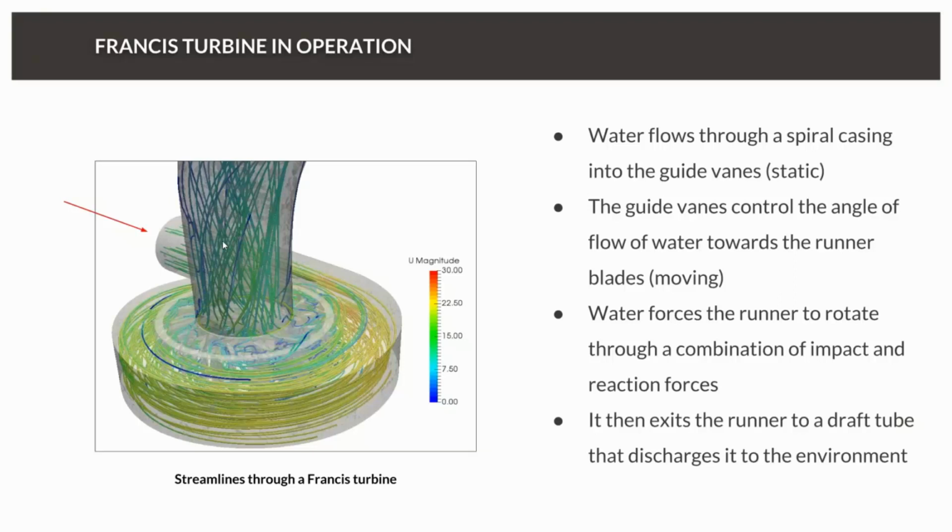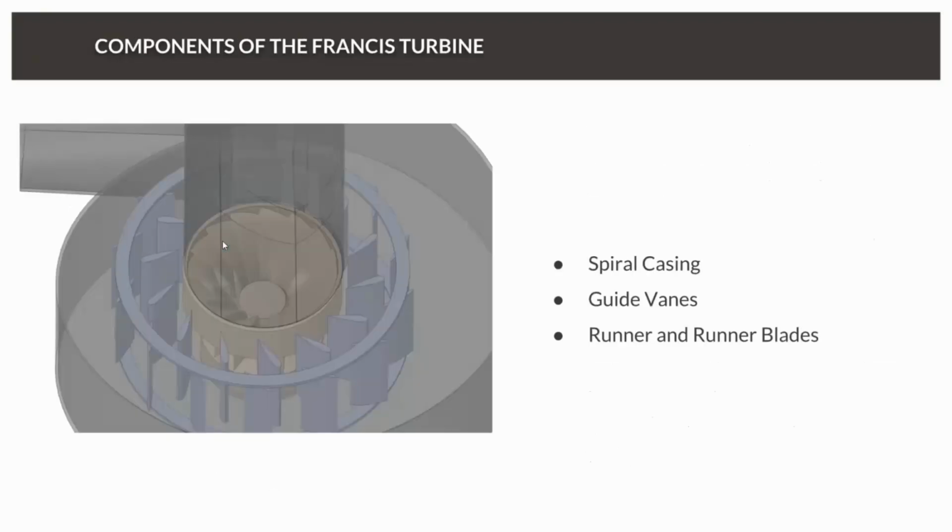And the interesting thing is this design is not too bad because the velocity is basically the same all the way around. So if I go back one slide actually, you can see on the left here the space where the water has available to move is much less than it has on the right, because a lot of the flow has already gone through and out of the draft tube. But we need to make sure that velocity stays fast, right? Because we want the loading to be pretty equal on the turbine and the bearings associated with it.